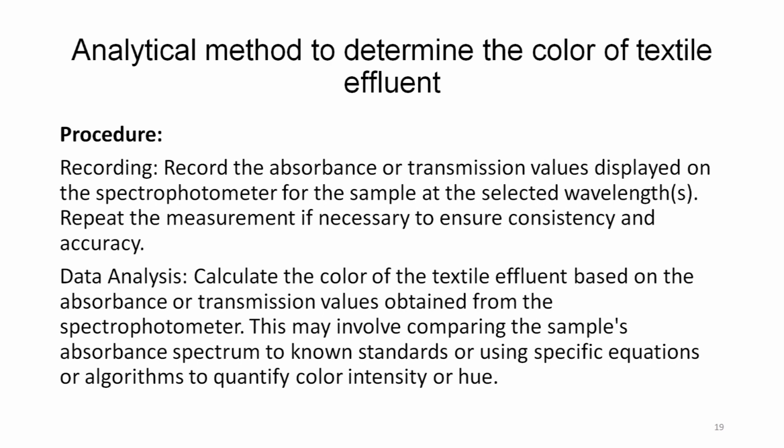Record the absorbance or transmission values displayed on the spectrophotometer for the sample at selected wavelength or wavelengths. Repeat the measurement if necessary to ensure consistency and accuracy.